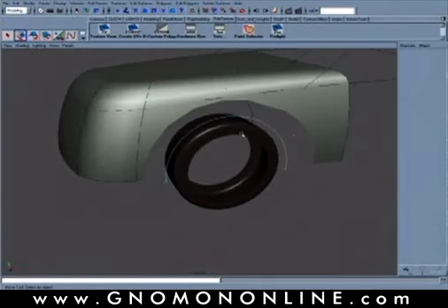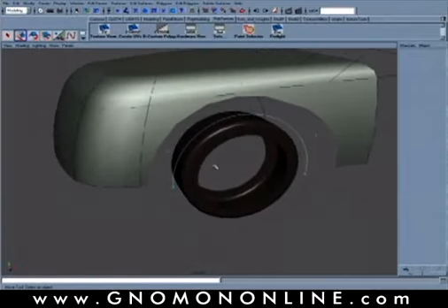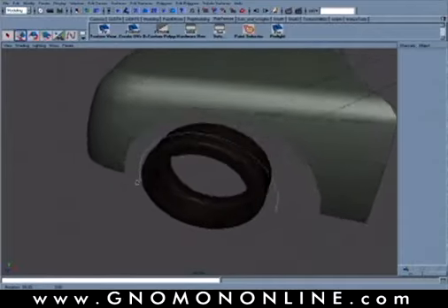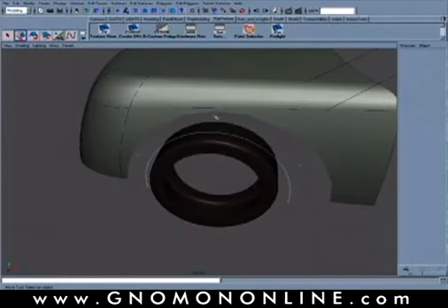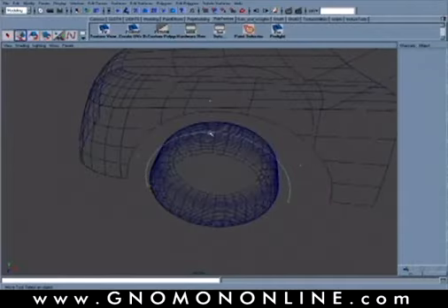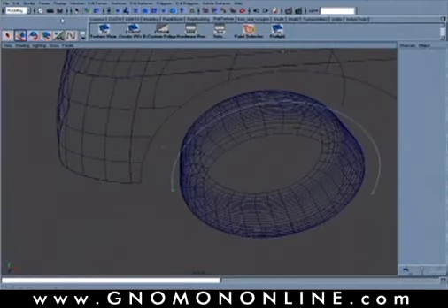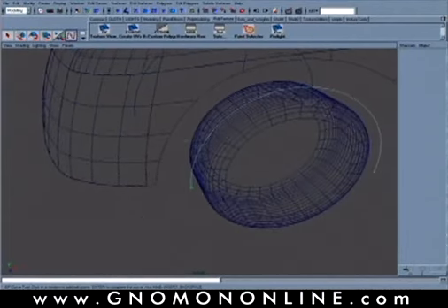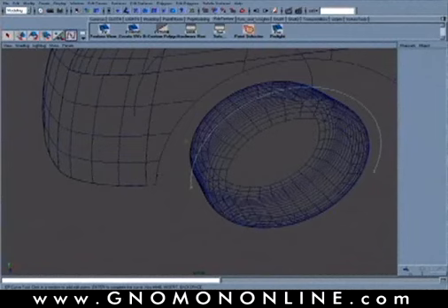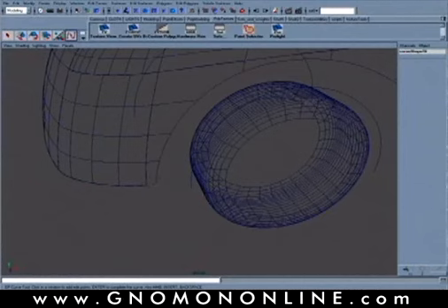We already have our trim back surface here. Next thing is to feed some new curves in here so that we can adapt a square surface in between there. So the way we're going to do this is go into our curve snapping and draw another edit point curve using the EP curve tool. And I'm going to want to snap this so that I curve snap just down along our trim edge so that it will stop right at the base there. And that'll be our first point.